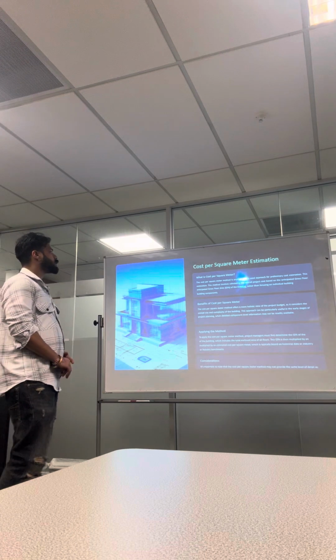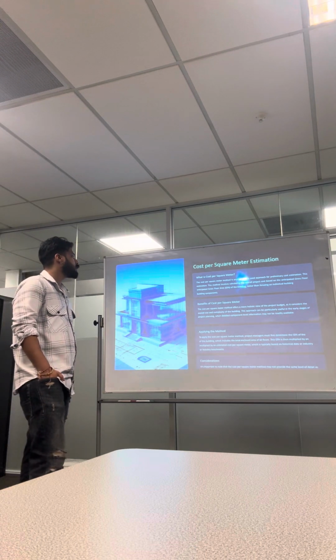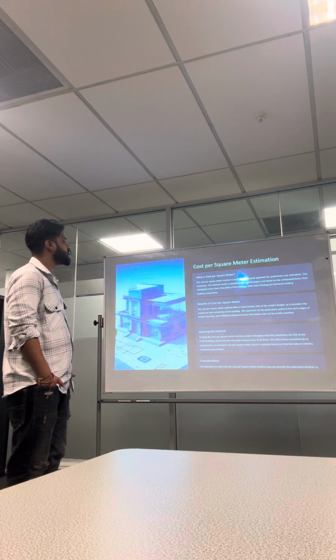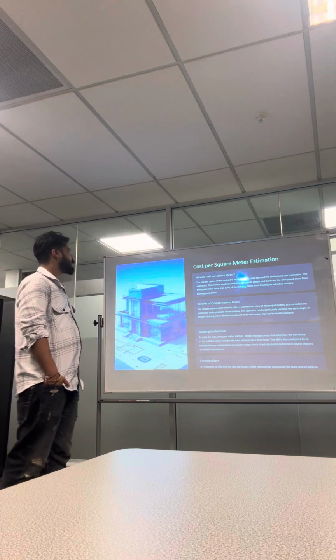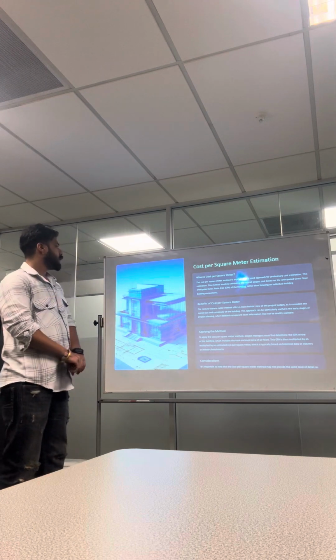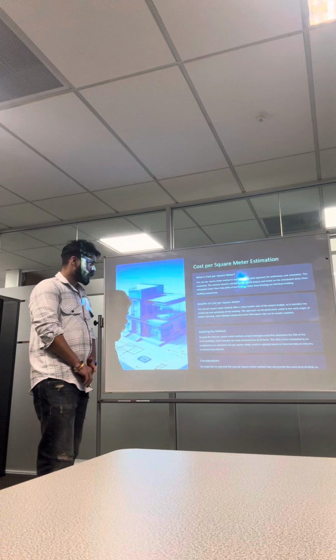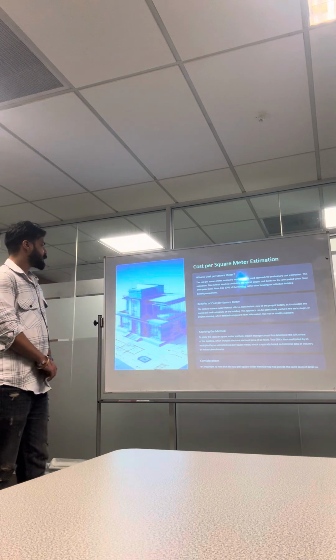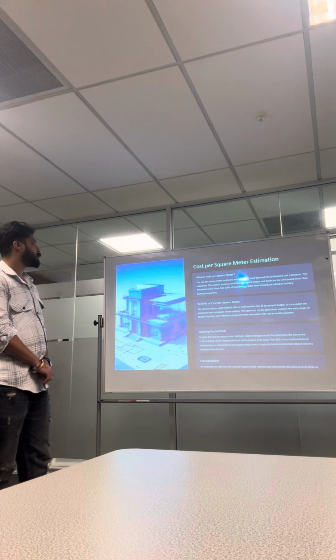Cost per square meter estimation. What is cost per square meter? The cost per square meter method is another commonly used approach for preliminary cost estimation. This method involves calculating the overall project cost based on the anticipated gross floor area of the building, rather than focusing on individual building components.